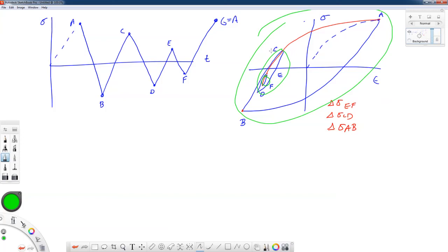Alright, so with this you kind of see what the rules are. You have to remember some of these points from time to time. We're going to formalize this into an algorithm, and eventually I'll show you a computer code that I've written in Fortran that will do rainflow cycle counting. But at this point, if you want some practice, try sketching your own time histories and doing hysteresis plots, assuming a little bit of plasticity.